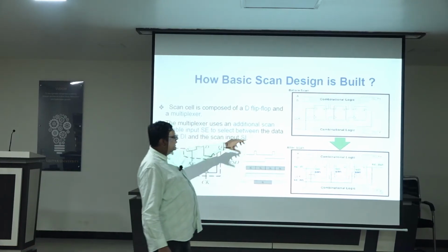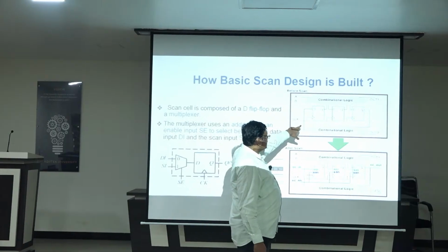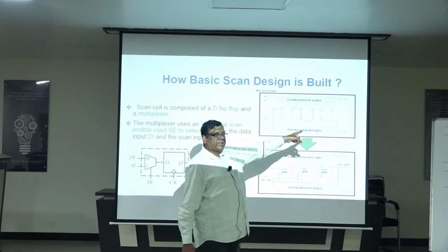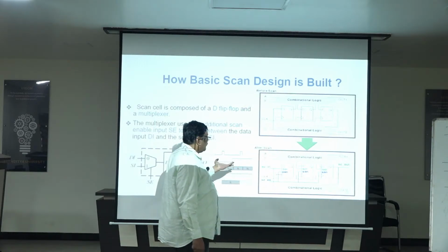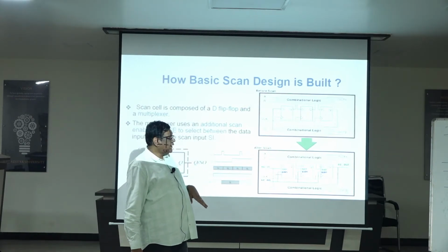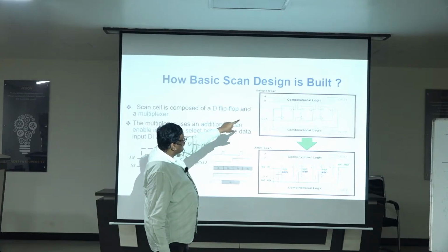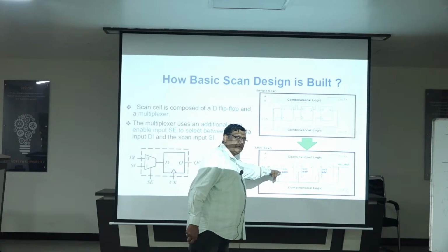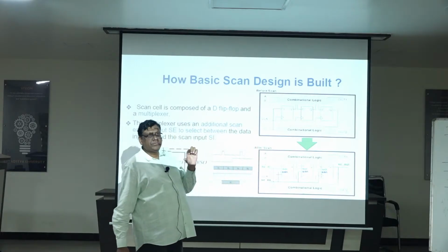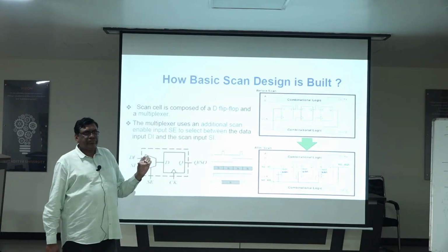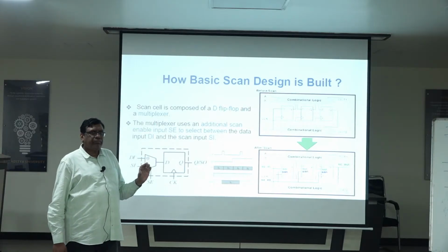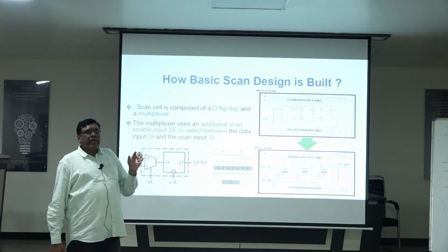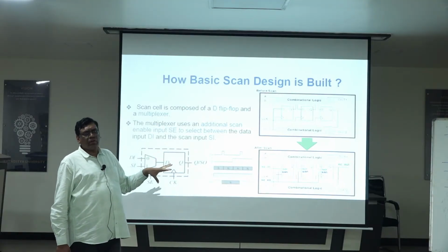So any RTL will be like this first diagram. A combinational circuit will be there, and all the flops will be there. Now, for scan, what I will do is, instead of an ordinary flop there, I will keep a scan flop. The D flip-flop I have changed to a scan flop. No other change. All the internal D flip-flops I have changed to scan flops.